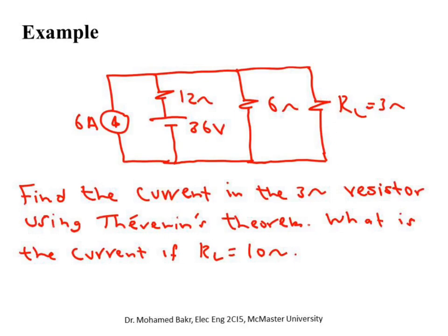What we'll do here, we'll simply create a port at this point and at this point, and then we try to find the Thevenin equivalent looking into this circuit. So I want to find what's our R Thevenin, looking from the load side into the circuit, and I would like to determine what is V Thevenin as well. So we'd like to find these two using Thevenin analysis.